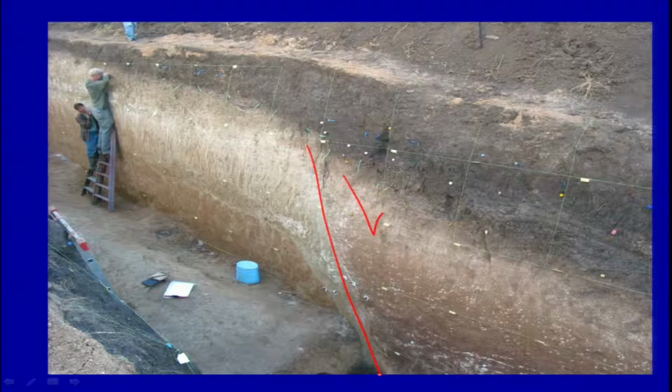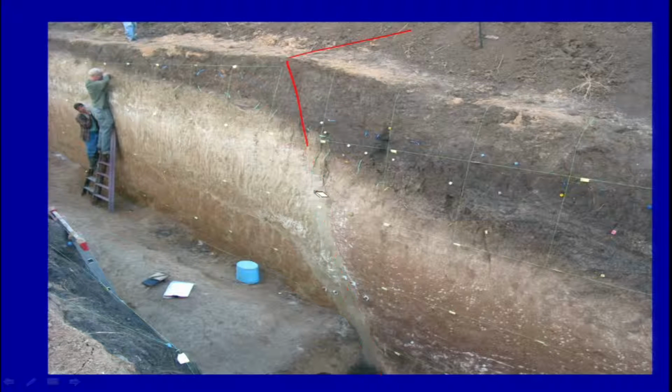Now what will happen is, this is the present day ground surface here. So when the next earthquake comes, this will rupture. So this will move further down, and this remains stationary here. So to avoid this, we need to identify the topographic expressions of such deformation.